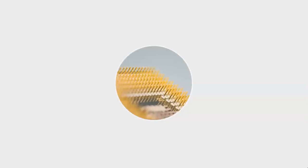The minimum quality is 0.3. This is fine, but when we generate a volume mesh, this will again go down. So I will go for smooth mesh. I need the quality of 0.6. Okay guys, 0.6 is very high quality. Automatically it will take care. See, I have a 0.5 quality. So this is so good.